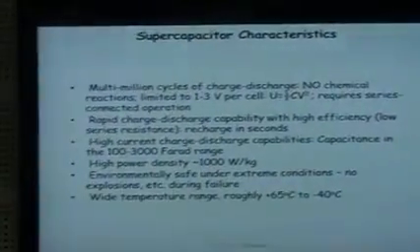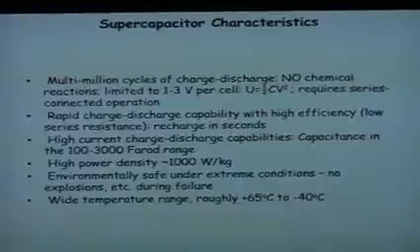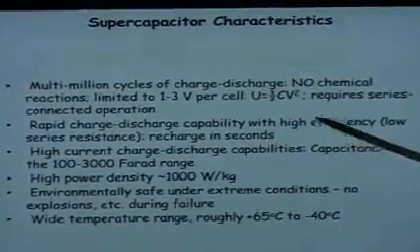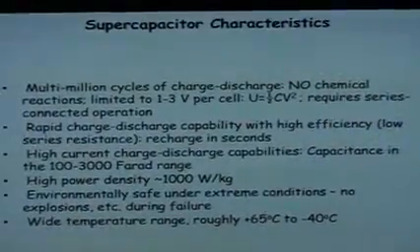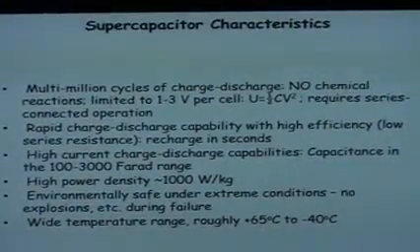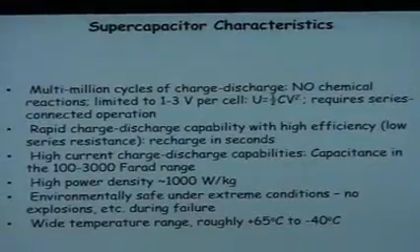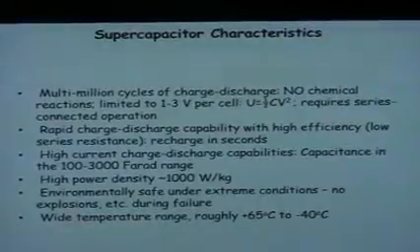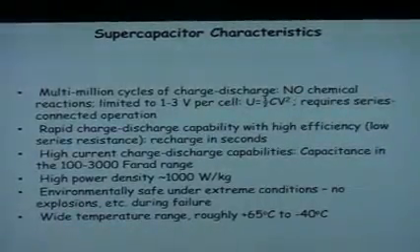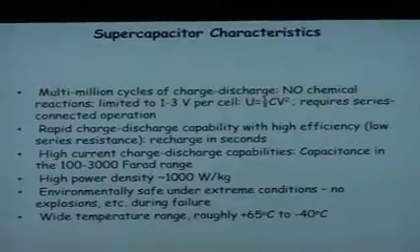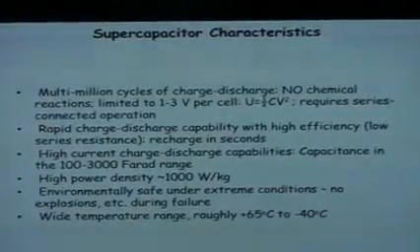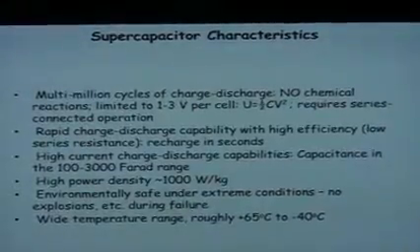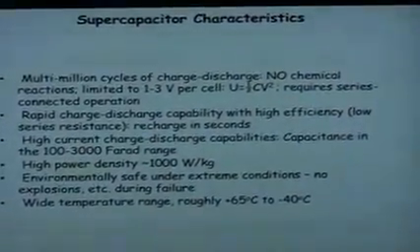So the nice thing about supercapacitors is that you can get millions of cycles out of them. And we talked about some of the energy considerations. We do need to bolster supercapacitors. We tend to have to go to multiple stacks of individual capacitors in order to achieve a high voltage. I mentioned that yesterday. You can have very, very high charge and discharge rates. And we'll talk about that some more today.